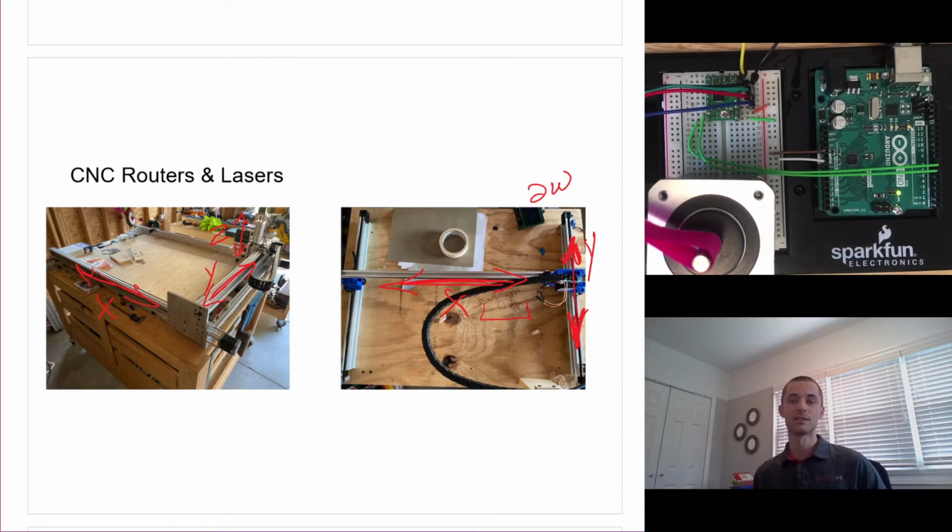For this particular setup, I actually used this one and tested out this laser diode. I tested to see how accurately I could etch circuit boards. The choice was either a CNC mill, where I'd actually cut away some of the copper on the circuit board, or essentially etch away the material using a set of chemicals.